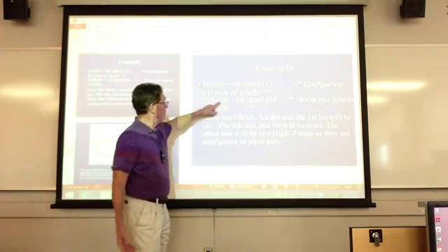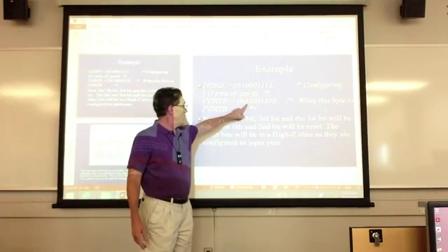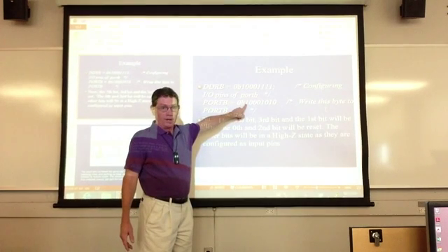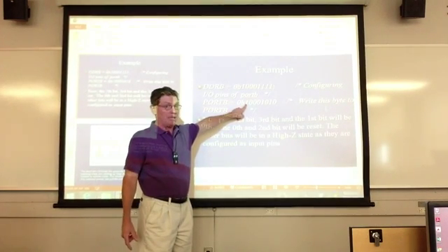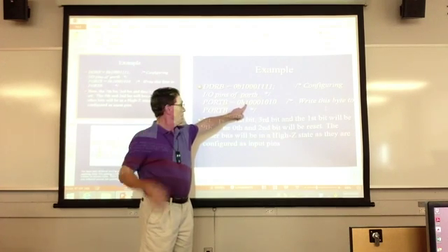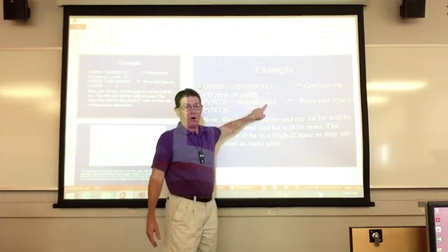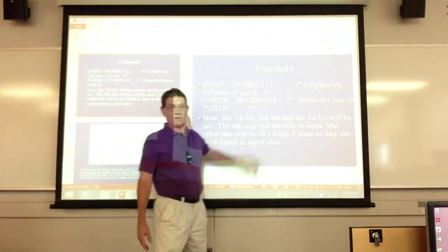And then I set port B equal to, this writes to port B. So I'm now going to write to port B a 1. So if there was an LED sitting on pin number 7 of port B, the LED would turn on. Off, off, off. The LED sitting on pin number 4 would turn on. Pin number 3 would be off. You know what I mean? You get my drift here?